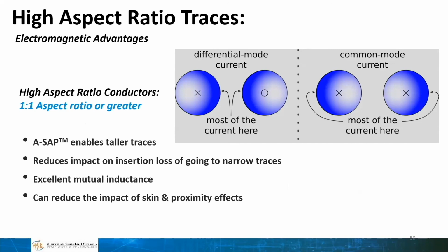One is, well, you just get more metal. You might only be able to have it 25 microns wide, but you could make it 37 or 40 microns thick, or maybe 50 microns thick, right? And get back some of the resistance loss from having made it narrow.